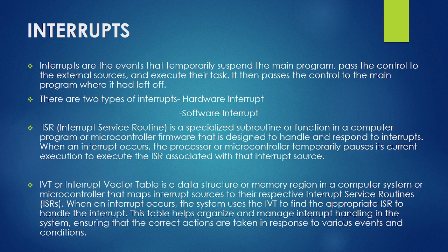And IVT is an interrupt vector table which maps the interrupt sources to their respective interrupt service routines. When an interrupt occurs, the system uses the IVT to find the appropriate ISR to be handled. So it maintains all the ISRs and finds the appropriate ISR that needs to be performed for a particular interrupt. So it manages all the ISRs.